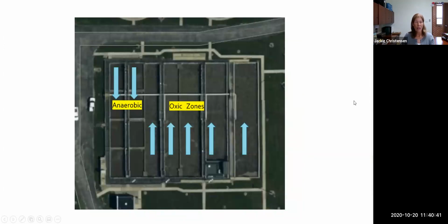So just zeroing in a little bit on the actual activated sludge. The screened raw influent mixes with the return sludge on the far left-hand channel, comes up to the north side or the top of the picture, and then goes down through 2 of the anaerobic tanks. Those are just mixed with low energy 5 horsepower mixers. There are 8 total of those.